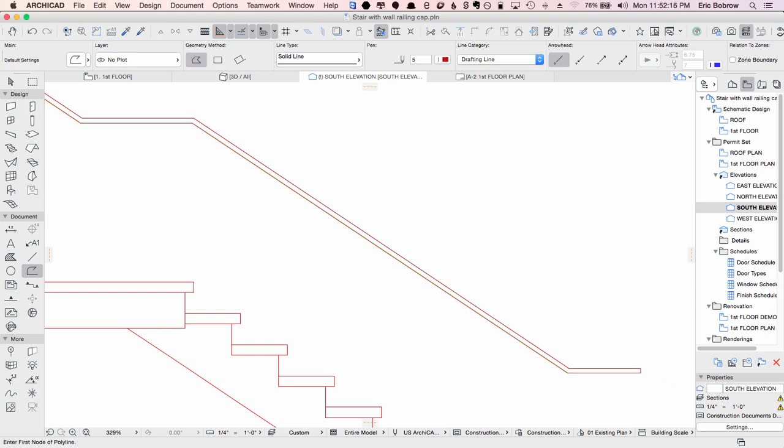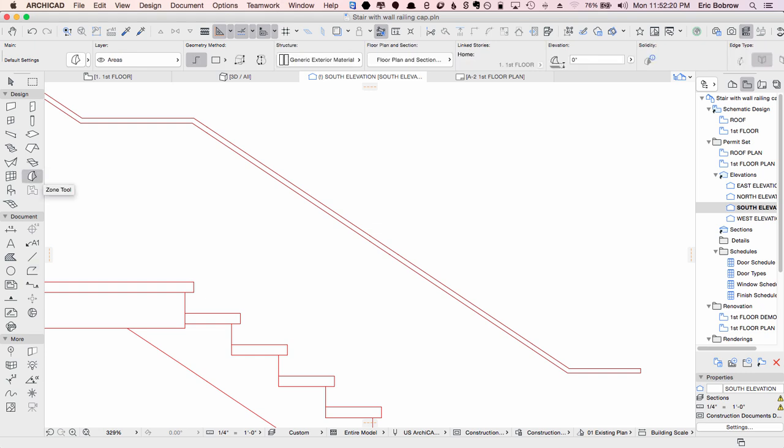So now we've got a closed boundary, and I'll use the Morph tool to create a 3D geometry, because right now we don't see any, there would be nothing to see in 3D. This is just purely 2D line work. So I'll hold down the magic wand key, which is the space bar on the keyboard, and when the magic wand comes up and click, you can see that now when I shift click, we've got a morph selected here.